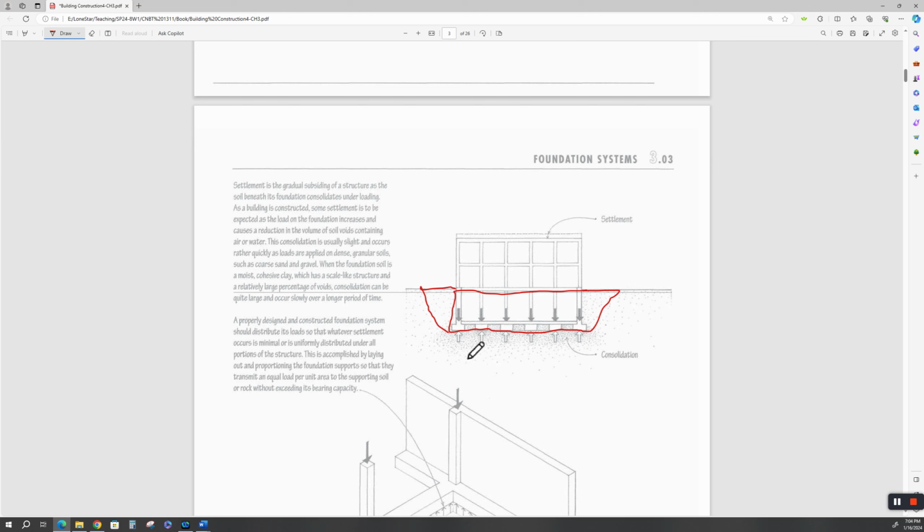Then it's not uncommon for the soil underneath it, when we remove this weight, to bounce up a little bit. It moves up, expands a little bit. And then we come down here and we start compacting this soil and get it down to the elevation that we want for the foundation. Our construction engineers shoot elevation and we get it compacted. Then we start laying in the concrete.